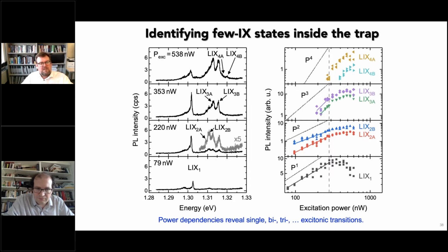So what will be very important are also methods to understand and to passivate these vacancies, either by terminating them with chalcogen atoms, taking the oxygen out. And people are doing thermal annealing treatments in, say, sulfur vapor atmospheres, and have shown that you can improve the quality of these materials a lot. I think it's again back to a materials physics question. I'm sure that a lot of these group to group and sample to sample fluctuations will be gone in a few years.